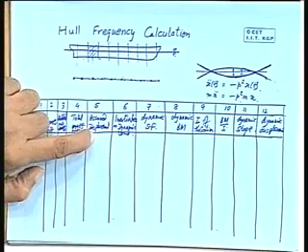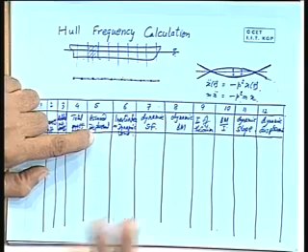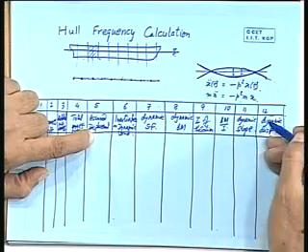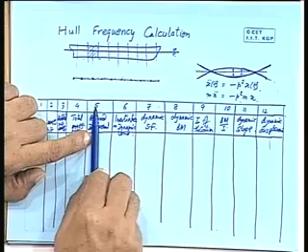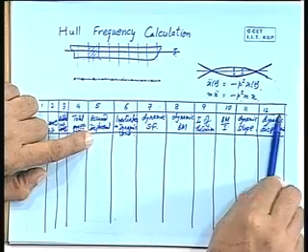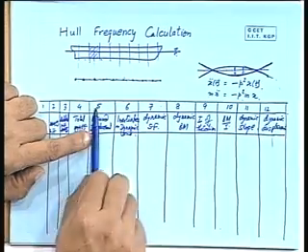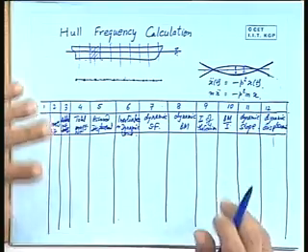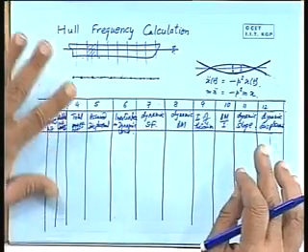If your assumed displacement is correct, if this is the mode shape, then this and this should match. If not, bring column 12 to column 5, repeat all this calculation and keep on doing this till you are satisfied. It's a very difficult job, time consuming.